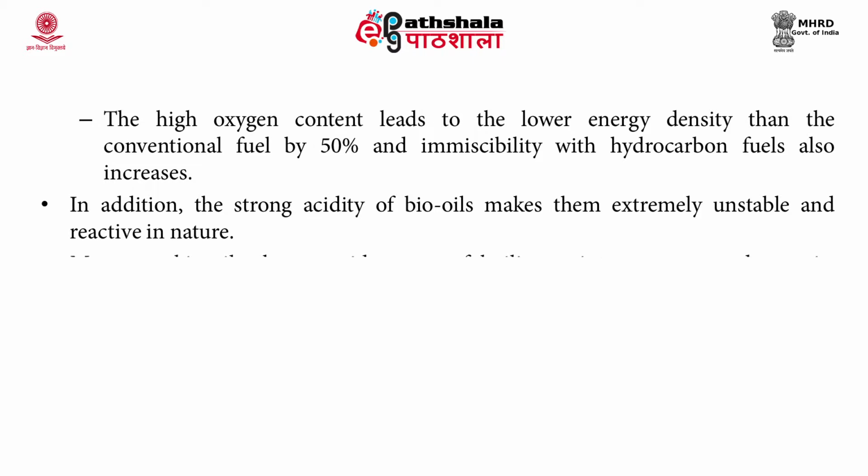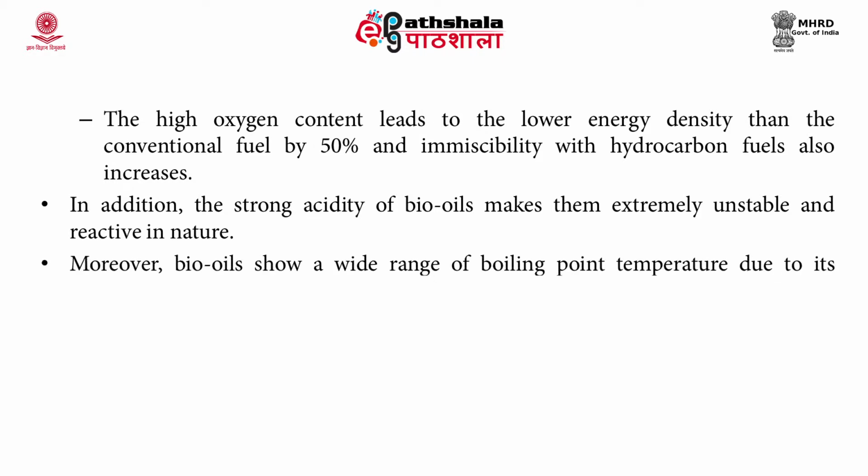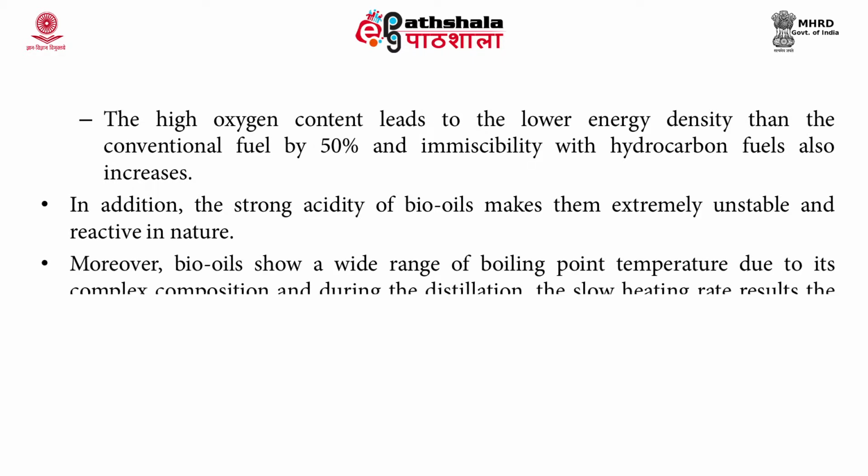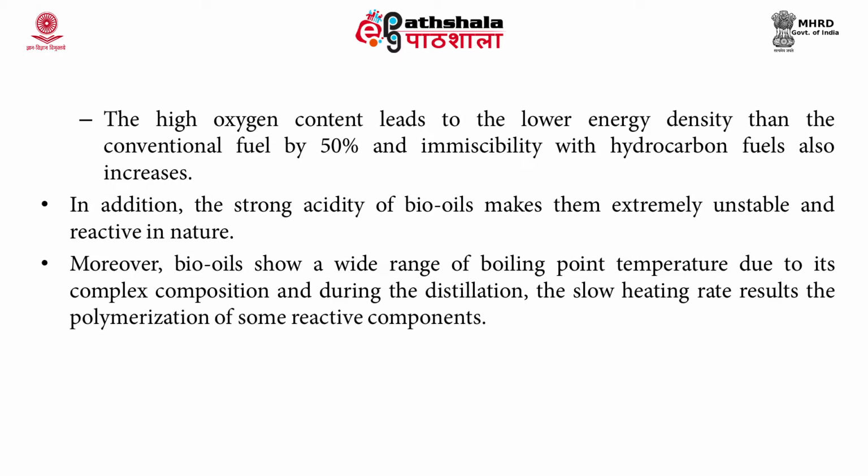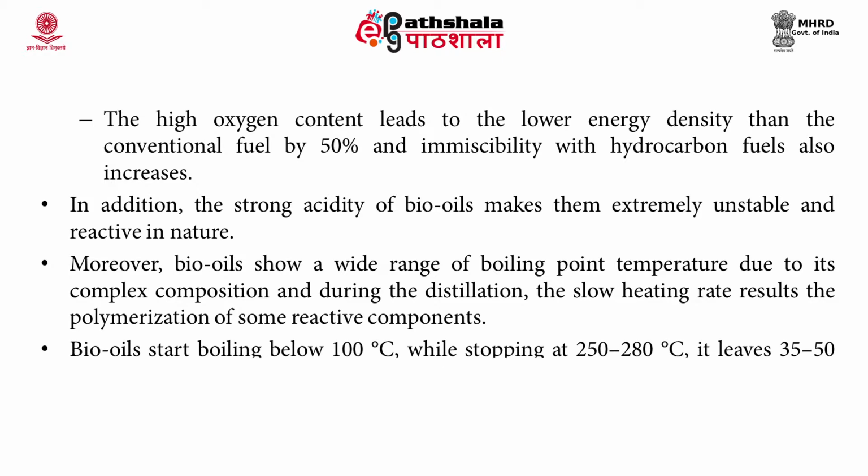It shows a wide range of boiling temperatures due to its complex composition, and during distillation the slow heating rate results in polymerization of reactive components. So, it starts boiling below 100 degrees Celsius, stopping at 250 to 280 degrees, and it leaves 35 to 50% weight as solid residues. The solid residues occur instead of oil production.